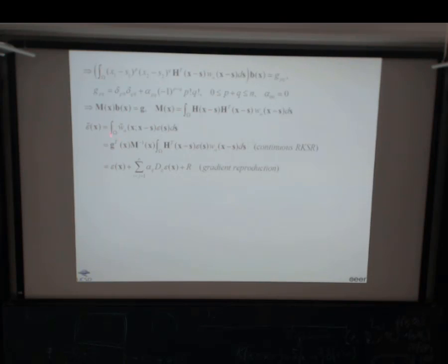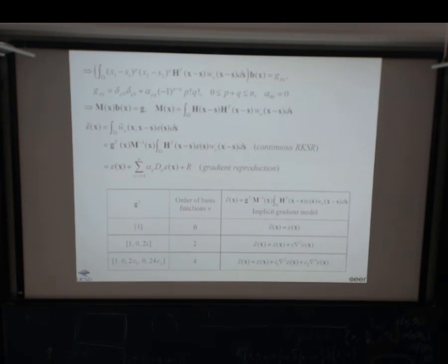Okay, so through this, then you know that by construction of this kernel, you can now represent the local strain plus gradient of local strain and use this as a regularization of your problem. Again, this will be exact if it is a monomial up to degree n. If it is an arbitrary function, then it is just truncation, and this residual you can estimate simply by Taylor expansion. Right? Okay, so just a few examples.